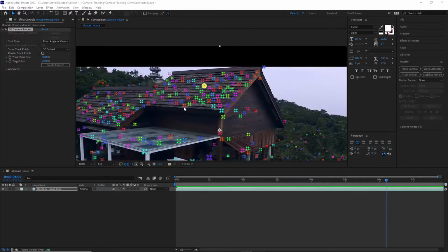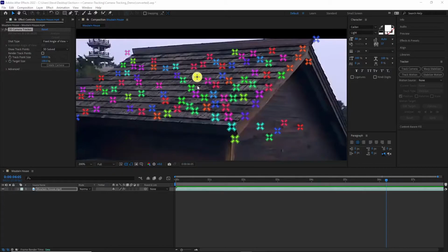Okay, so just to revisit what I said earlier, when you're using the camera tracker, it analyzes the camera movements, but it also analyzes the 3D data, so data about three-dimensional elements within the footage. Like I said, to define a plane on a three-dimensional plane within the footage, it uses 3 track points.